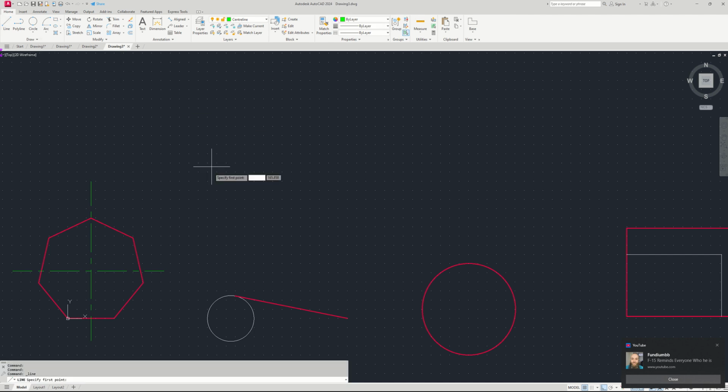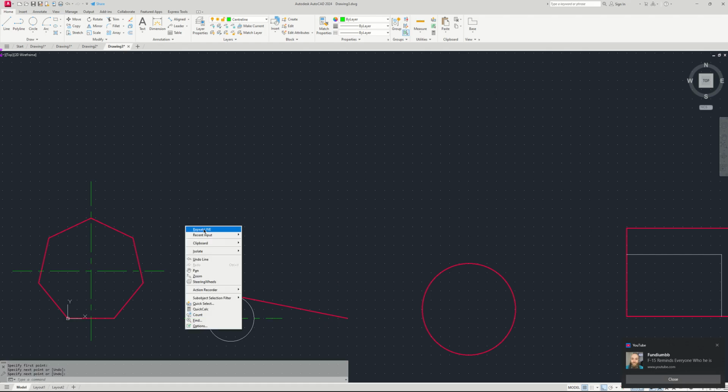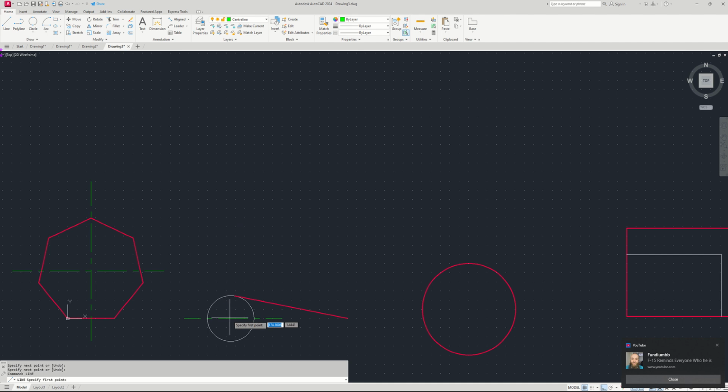Again, just use the line command. Hover your crosshairs over the object, anywhere on the circle. It highlights the center. Now I can move that away quietly, smoothly, and then I draw my horizontal center line. Okay, right click, enter. Let me draw the vertical one, repeat line.